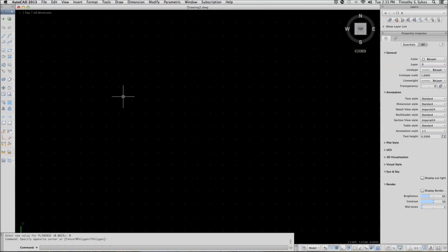This is exercise 12-1A, drawing with polylines. I've begun a new drawing from scratch. I have set my grid to 1/2 inch, my grid snap to 1/4 inch. I've zoomed all and turned on polar tracking. I've also set grid dots for my grid. That's a personal preference. That's not something that you have to do for this particular exercise.